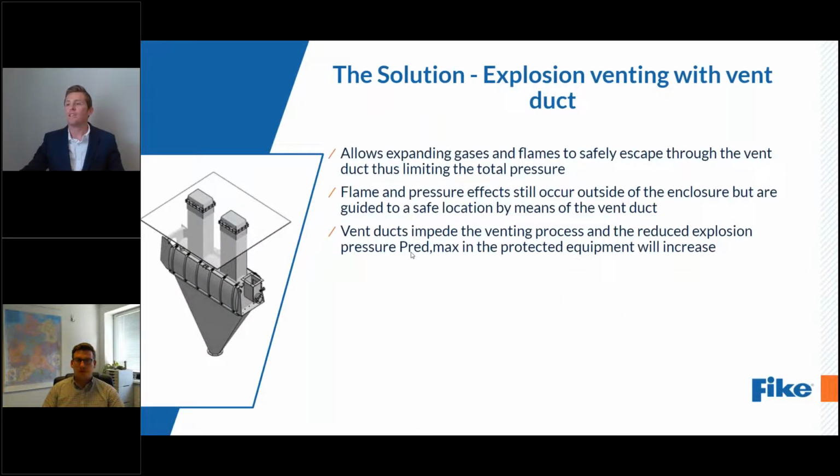Vent ducting. I'll be fast here, but there's an explosion vent, you have the enclosure indoors, and you need to go up and out the building with the explosion, or maybe out the side. It has the ability, although whenever you start calculating for that vent discharge duct, you have to decrease the efficiency of it because it doesn't allow for free venting of the explosion event.